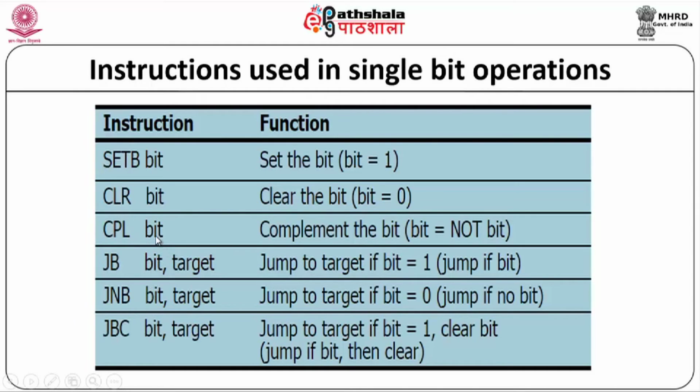So, if I am giving CPL P3.1, what it does is it changes that particular bit from 1 to 0 or 0 to 1. These are all bit operations done through this kind of commands. JB, these are all operations.